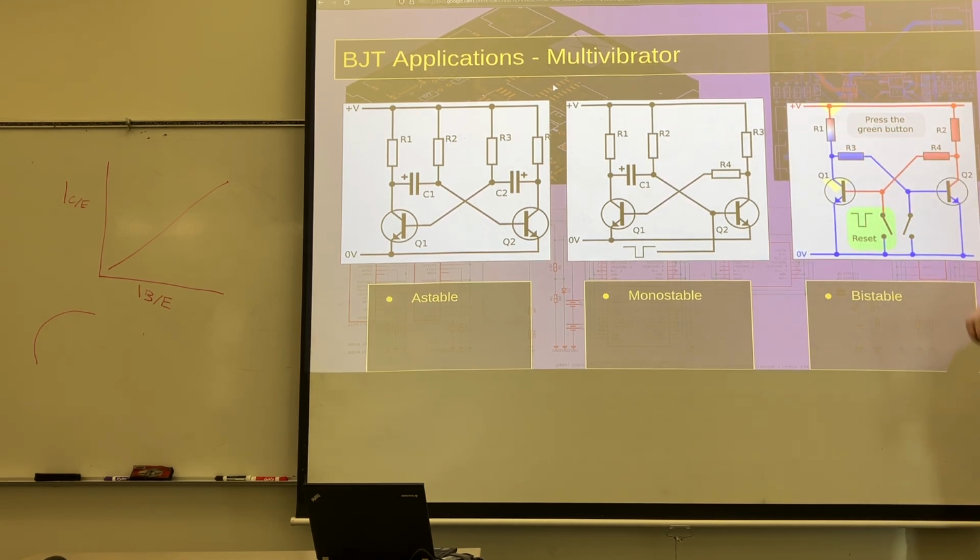Is everyone with me so far? I need to take this really step by step because this gets kind of not great. So high voltage on gate, this is conducting. Because this is conducting, all voltage drops here. 0 volts here. 0 volts on this. This is not conducting, as we can see. In a static equilibrium situation like this, it's very easy to understand. When you go over to that one, it's a lot harder.